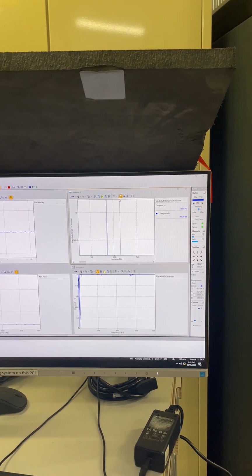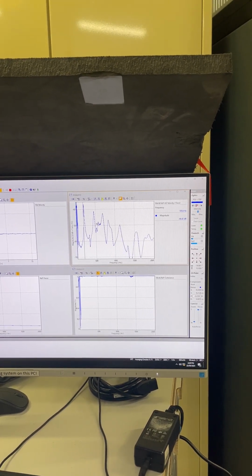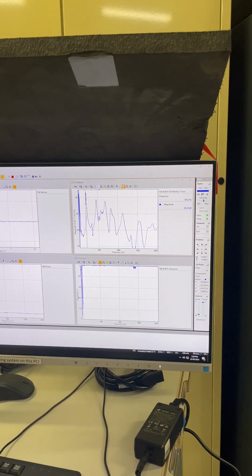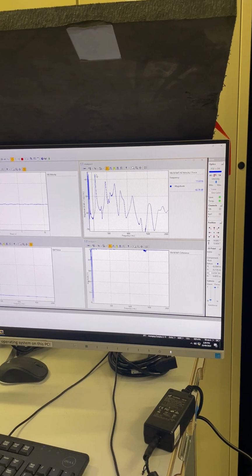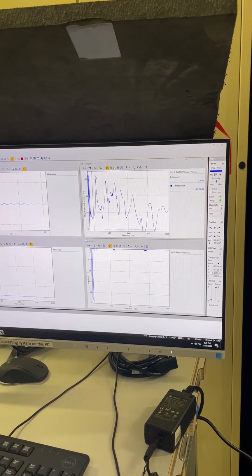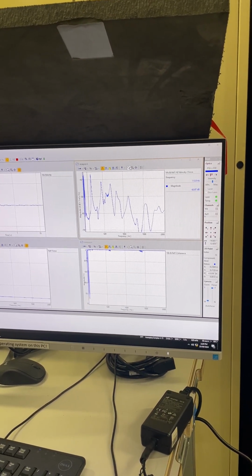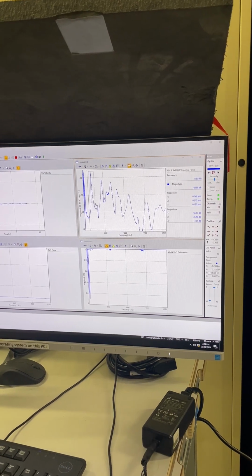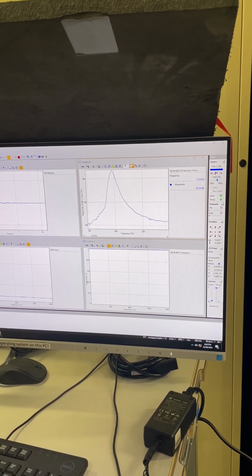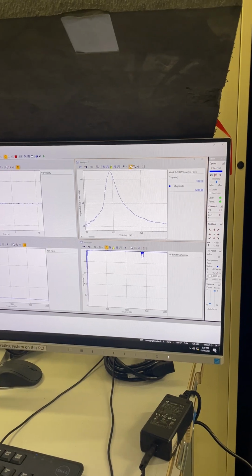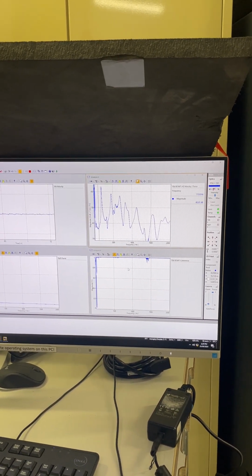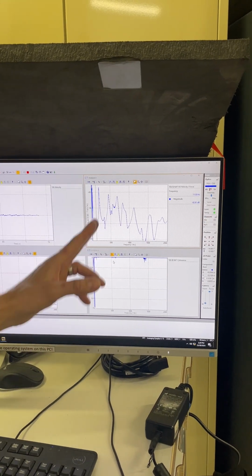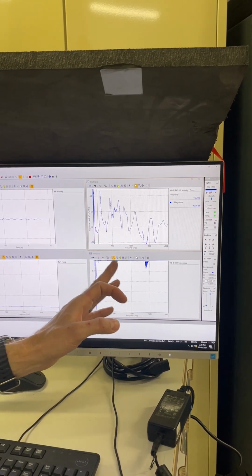So there are a couple of resonant frequencies which we can see within this spectrum here. Actually, this sample has a couple of close modes, very close together, so there's a couple of peaks in there which we can maybe just about pick out. They're basically contributing to the same peak in the spectrum here, another couple of resonances up here, and wherever we have resonant frequencies, we want to ensure that we have good coherence function.